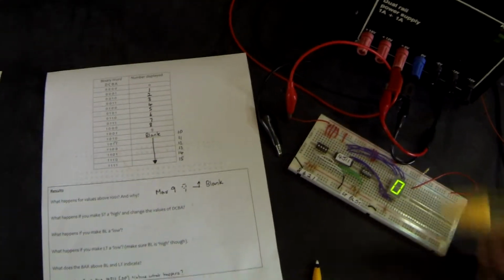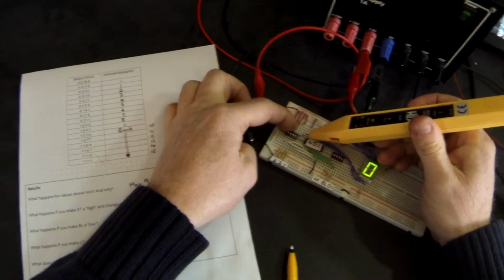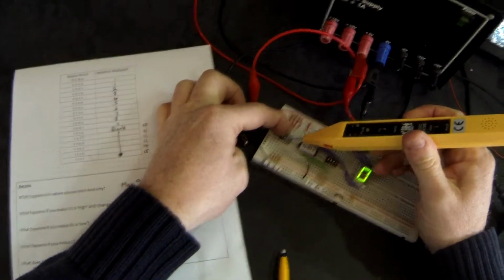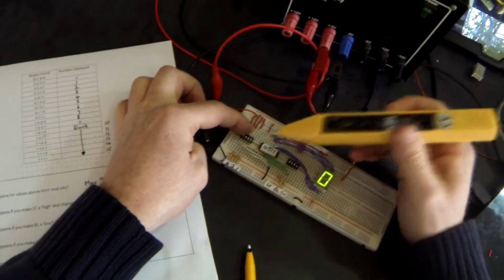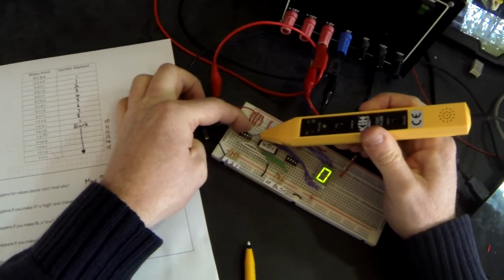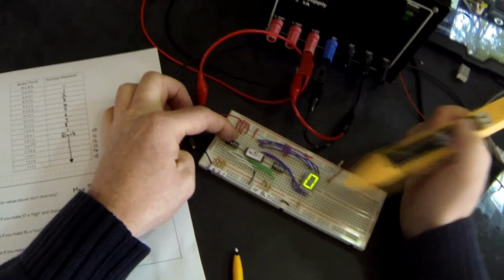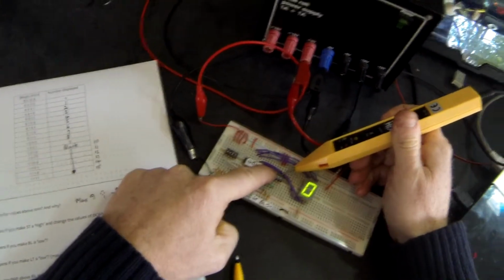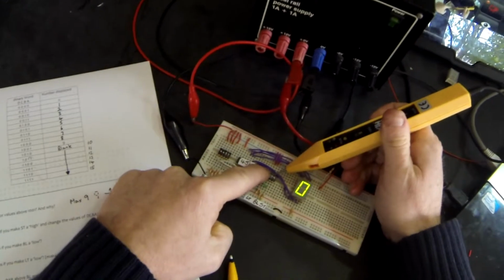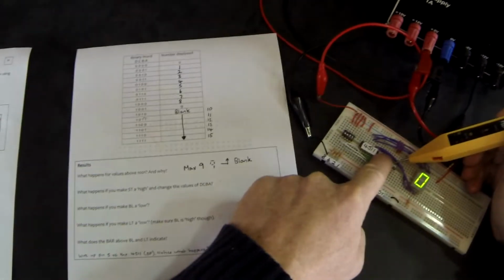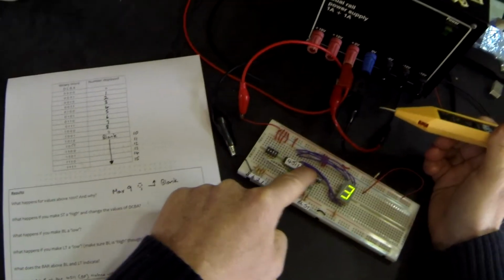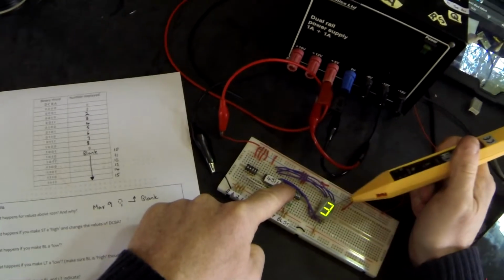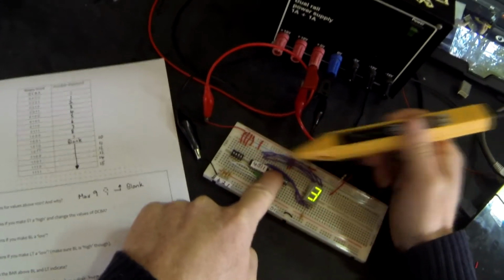And 0 is still being displayed, but now I'm going to change it from 0 to 1. And nothing has happened. Let's try changing it to 3, so I'll change B as well. Nothing happens. So let's put ST back low again, because clearly with it high it's stopping, and immediately the 3 that we put on there is displayed.